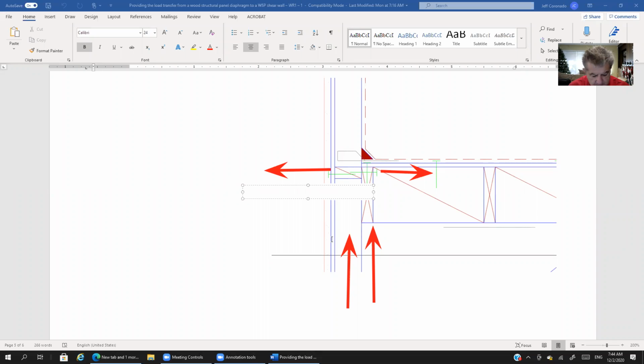And I'll even write that out for you. So we have nails, well, I'm going to draw it out in yellow just to not switch, but all right, we would have nails in withdrawal. And let me right away cross that out. We do not, as structural engineers, we do not like nails in withdrawal. The capacity that a building code gives us for a nail in withdrawal is very low. More times than not, what we're going to find is that nails in withdrawal is not adequate.